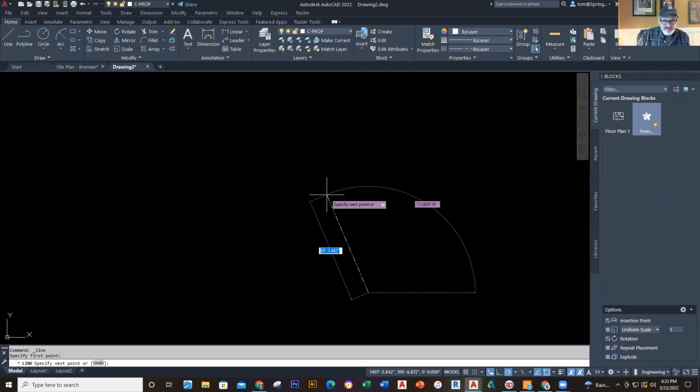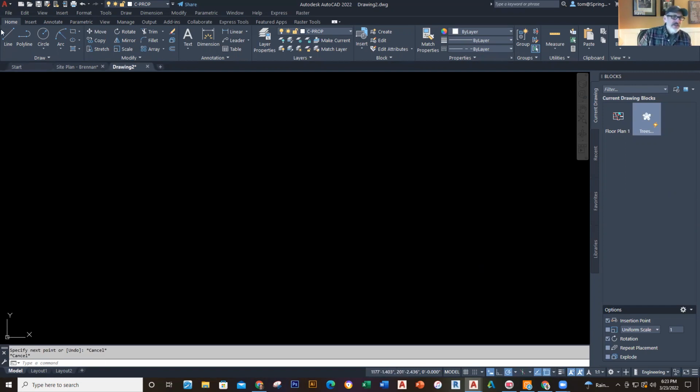So I go here, and it's going to be 48.92. Oh, I have to put the @ symbol. Sorry, one more time. Line. We'll start here, and we'll go over here, and type in @ 48.92 feet less than, and then I've got this to type in: N 17D 30 minutes 9 seconds west, like that. All right, so that's okay.